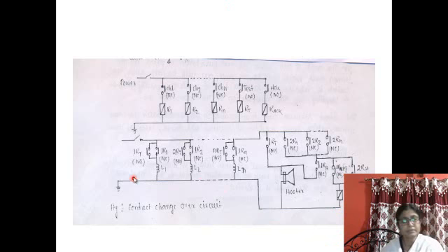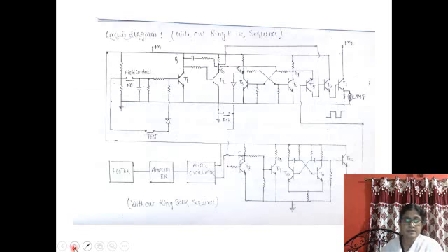The only thing is how the corresponding lamp will glow on and the hooter will produce the audio signal, and after acknowledgement how this can be turned off. There are 5 sequences for any annunciation process, and all these 5 steps can be explained from the diagram.